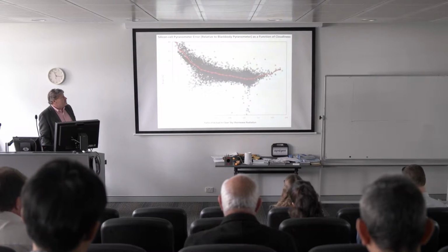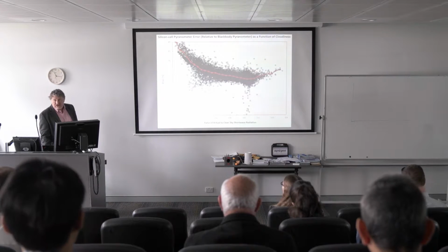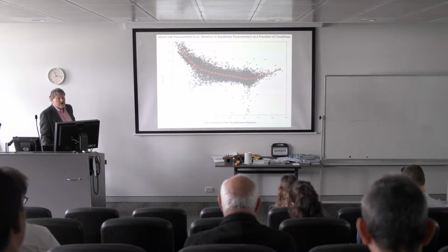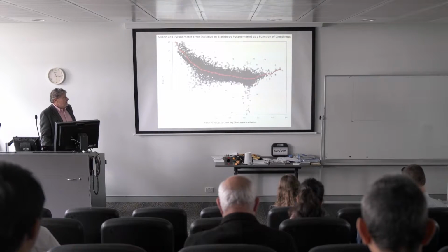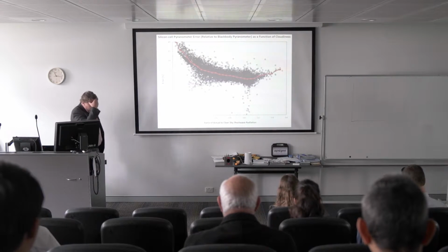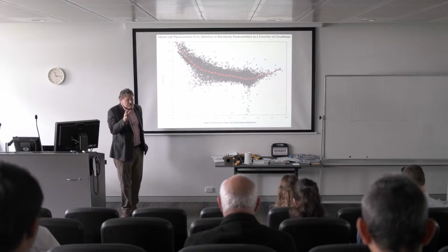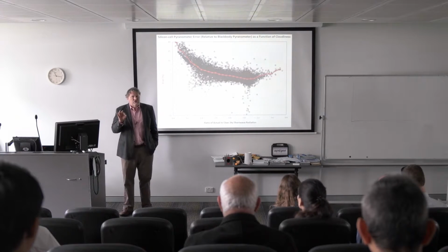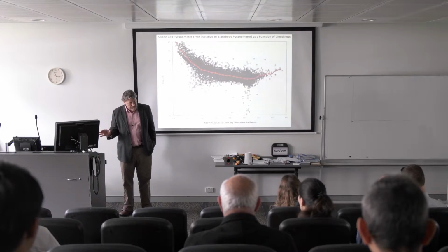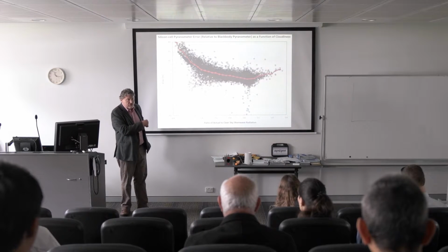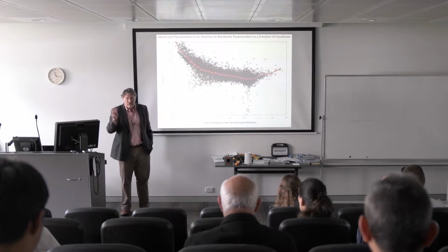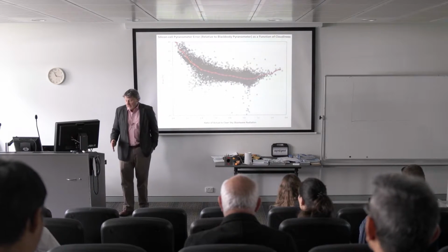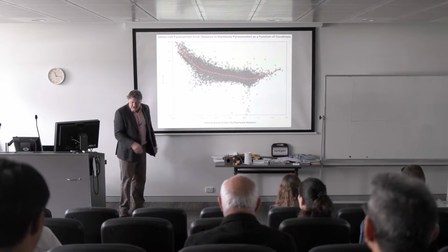But on severely cloudy days, or significantly cloudy days, it's a pretty big error from silicon cell pyranometers. The good news about this is the cost of black body pyranometers continues to come down. And because of these errors, we've sold a silicon cell pyranometer for a long, long time, and we just tell people about these errors.